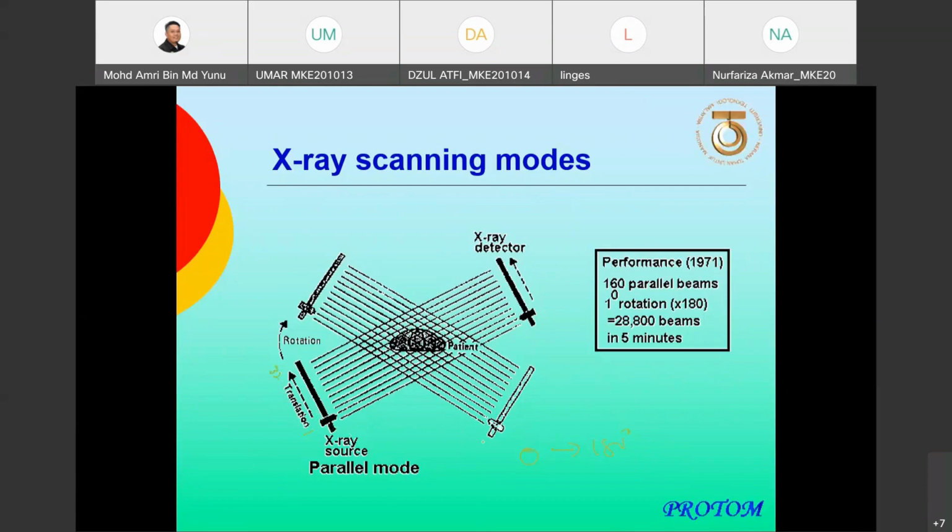So let's say at 0 angle, it will make a measurement from location 1 and then move the source and receiver in parallel to the second spot until we complete 32 measurements. Then move on to the next angle plane, 1 degree, and repeat the translational measurements 1, 2, 3, until finished. So this scan is happening in, for example, 5 minutes.